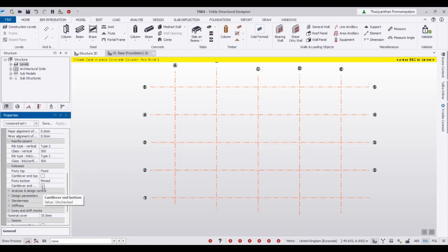The worst thing is the software ignores the torsion, because in the standard setting, normally, if torsion exceeds a certain amount, the software automatically ignores it, right? Then you completely do the design, but it's not workable. Okay, I leave it first. This one. So my column bottom is pin, the top I will leave it because it's taking the frame stiffness.